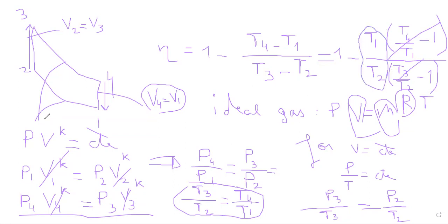And to do this, I go back to my figure. Points 1 and 2 are relative to the compression phase. Okay? And during compression, we have that it's an adiabatic process, PV^k equal constant. Okay? But also for adiabatic processes, I can deduce a relation between V and T. Because we know that for ideal gas, PV,